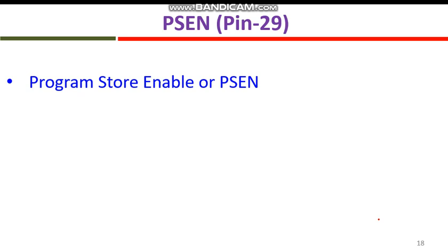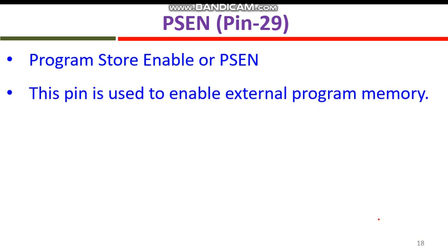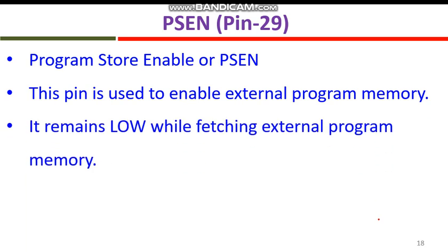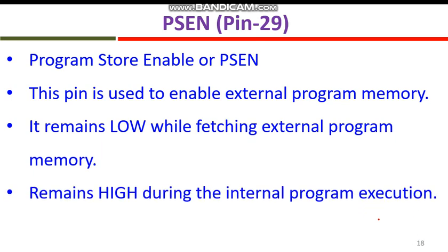PSEN is called program store enable. This pin is used to enable external ROM, or we can say external program memory. So it remains low while fetching data from external ROM and remains high when the data is accessed from internal ROM only.